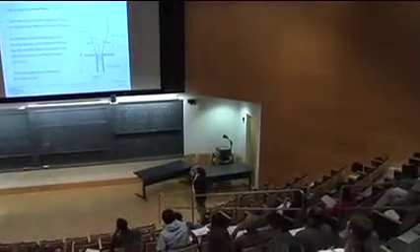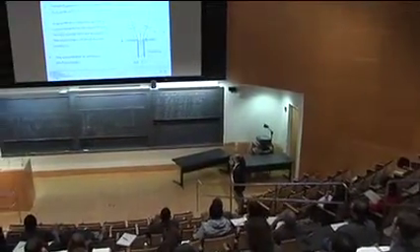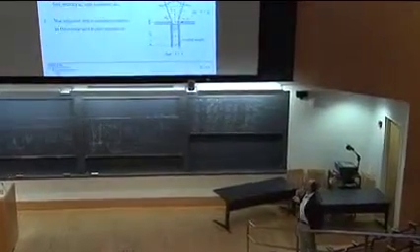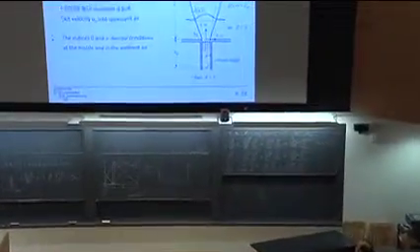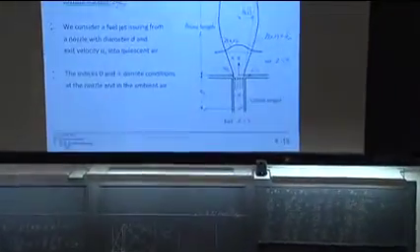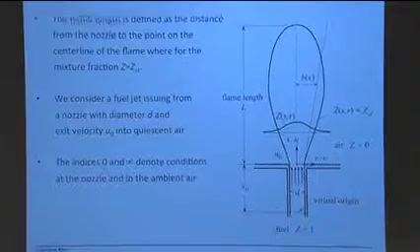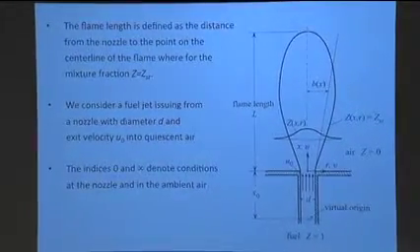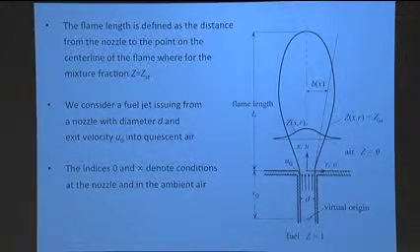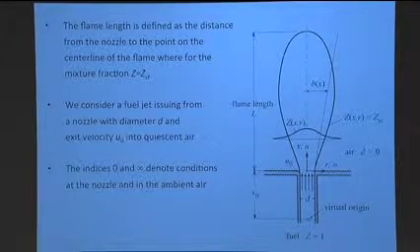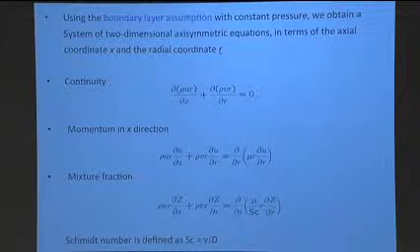Stoichiometric, which kind of means that the flame length is where the stoichiometric contour hits the center line. Okay? And because now, interestingly, we can bring the flame length back to this non-reactive scalar, essentially we just need a solution for this non-reactive scalar and anything else that's related to this. So these are the equations: continuity, momentum equation, mixture fraction.